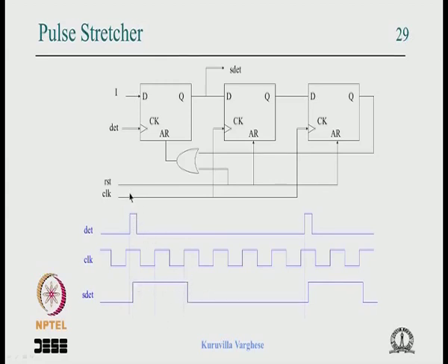So what we do is that we have a clock and reset, and the clock goes to these flip flops, but this catching flip flop takes the pulse as its clock, and the D input is given 1. So what happens is that when the pulse comes, this detect, I am calling this DIT, and this is the synchronous detect, you see that it goes high. So the detect comes on the next clock edge.